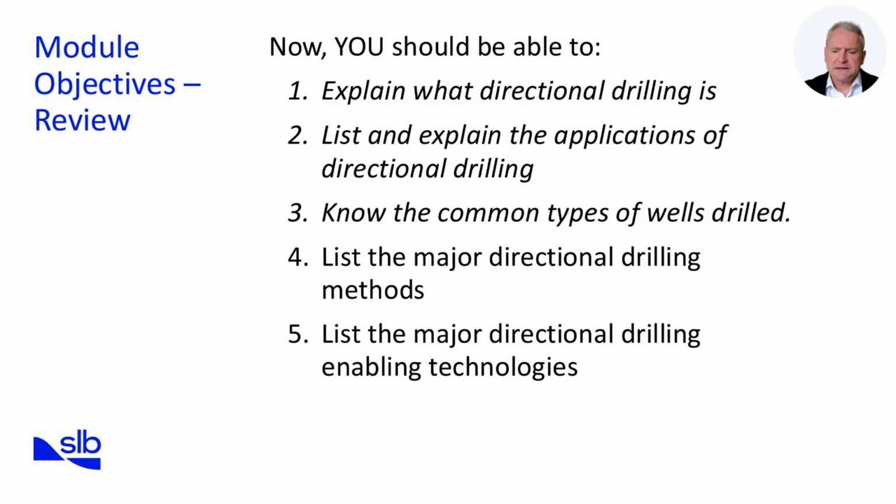We then progressed this into geosteering, where we use real-time data and earth models to keep the bit in the optimal geological zone actively. Finally, we reviewed the common limitations in directional drilling, including torque and drag, hole cleaning, wellbore stability, and hydraulic limits. This concludes the module on applications, objectives, and limitations.